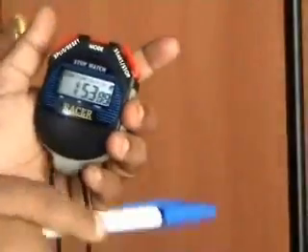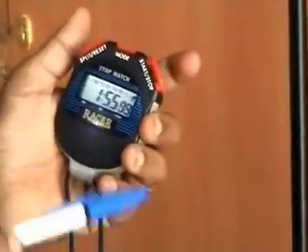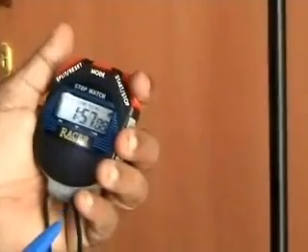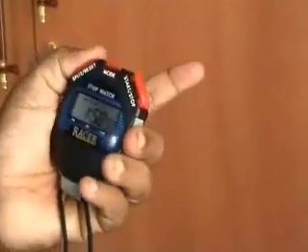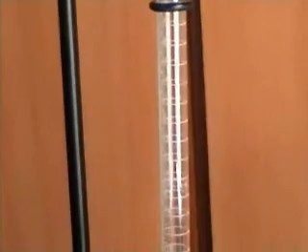Okay, let's assume it is at 65 now and it's going to 70. So for the last reading, you may press stop. Note down the reading, and then when you reset, it will go back to 0. So this way you can conveniently note down the time. As in torsion pendulum, note the time up to microseconds. So like this, again pour the water for the second trial.